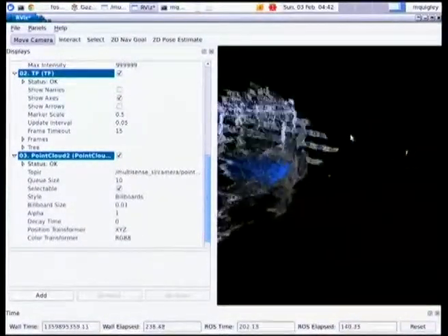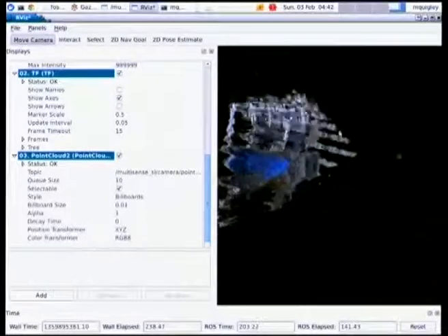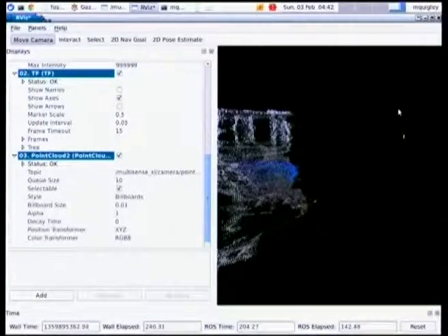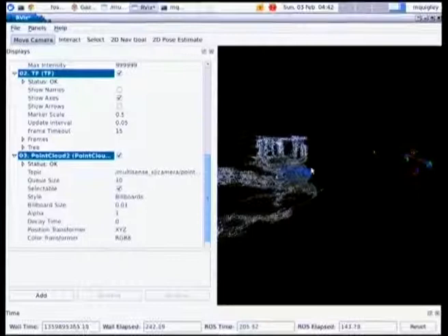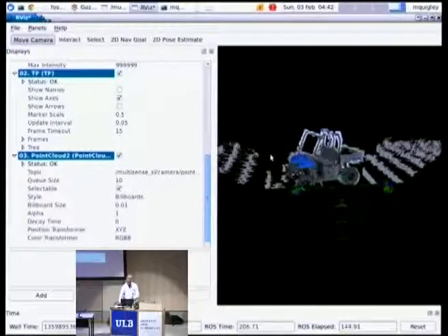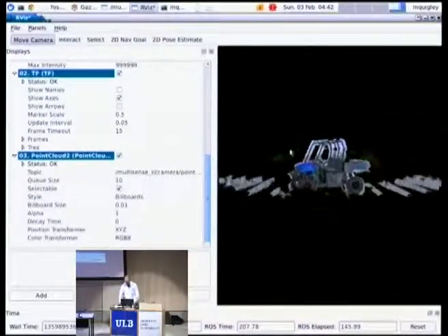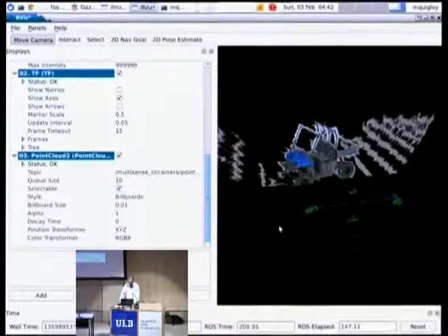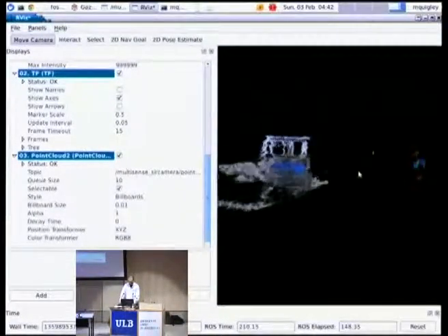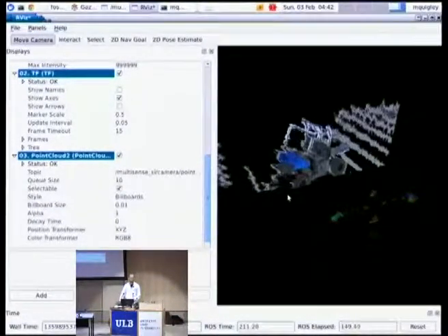So you can see, just like real stereo vision, it's not quite what you'd hope for. It's sort of wiggly and squiggly, and there are pixelization and quantization artifacts, and that's kind of what you get in the robot. And this is actually pretty good. We can corrupt this data more if needed. The other nice thing with the logging utilities is you can just dump all your messages to disk and play them back later.